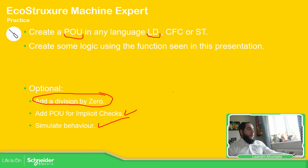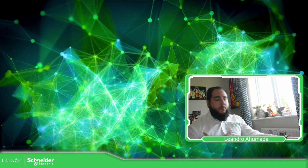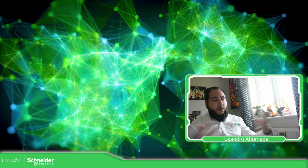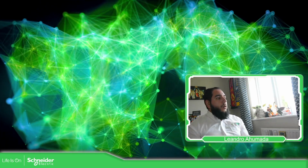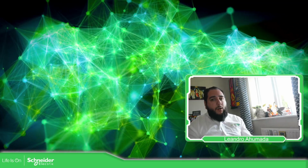As you can see here, if you need to make a formula or something, I strongly recommend to use structured text rather than ladder. It's going to be a long instruction that you need to do. But if you're still feeling comfortable with ladder or CFC, just go on.